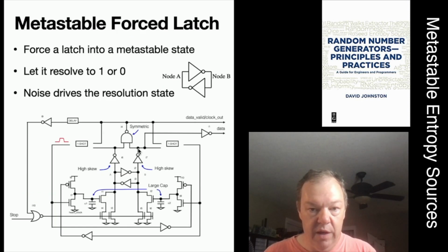But at some point it will diverge and it'll get a 1 and a 0, and this will lead to a pulse being made here, which goes through a little delay, and it goes around here, and that pulse then pulses these clocks again and causes the process to repeat. So this loop around here, once the resolution is detected, as in we get a 0 and a 1 or a 1 and a 0, not a 0 and a 0, the circuit then pulls both sides back down again, and the process starts. There's a big loop, and this circuit self-oscillates.